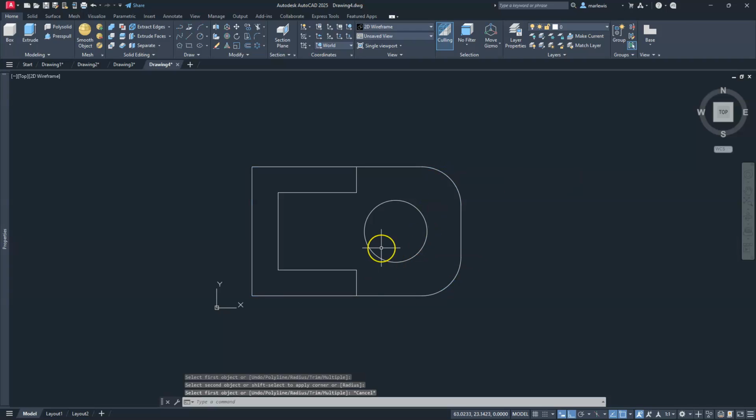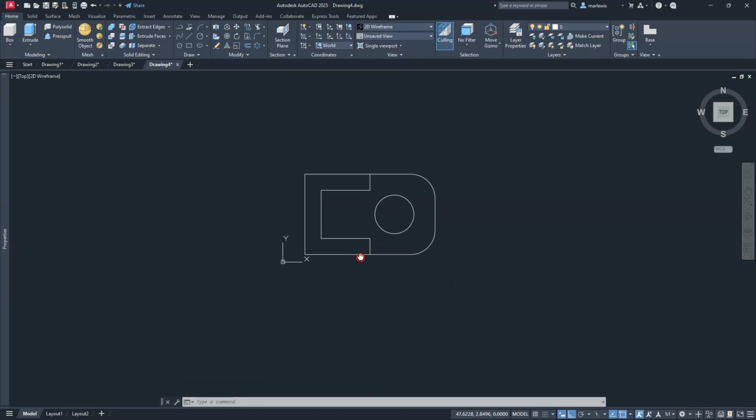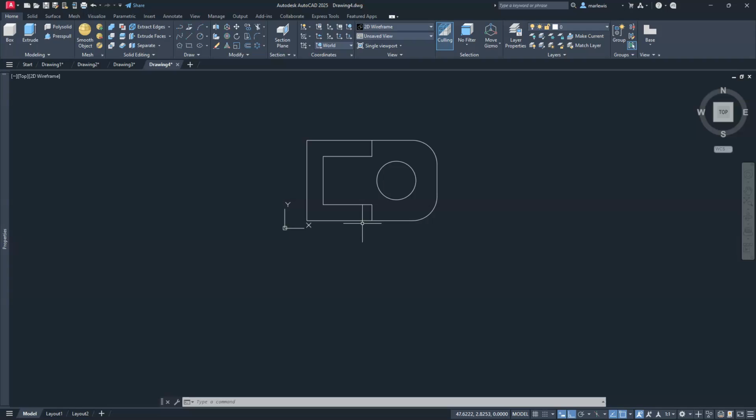Alright. So this is our shape if we were drawing it just using 2D AutoCAD, but remember that this is a 3D. 3Ds have to be defined by closed profiles, okay? And when I say profiles, what I'm really meaning is a closed polyline, preferably. So what I'm going to do first is I'm just going to go ahead and copy this portion here down to the bottom. So I'm just going to grab those and copy them down like so.